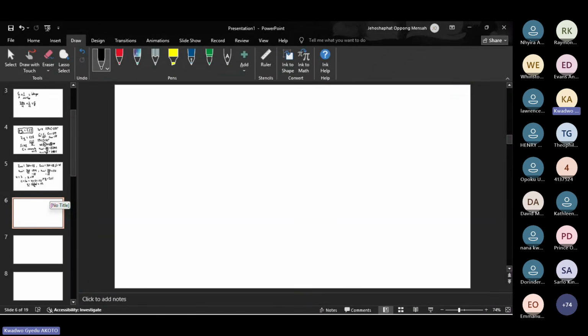Please, determine the number of bottom conductors for coil 1 if its top conductor is given the number 1. So all this question is trying to tell us is that if for coil 1 we have top conductor 1, where will its bottom conductor be? To do this, we need to know our coil pitch.